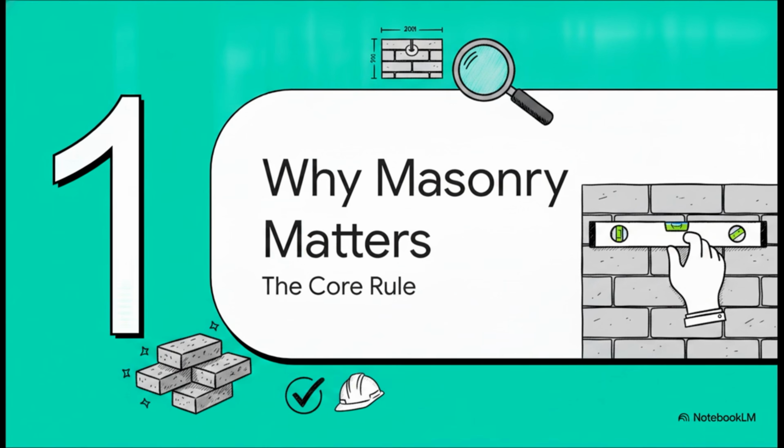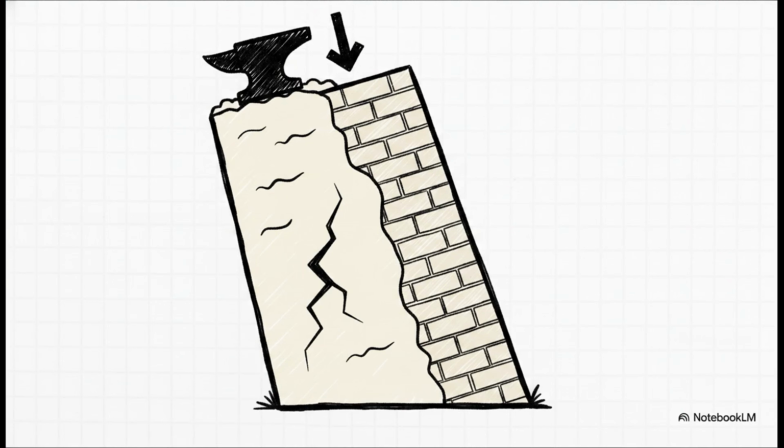Let's talk about why your rigorous QA/QC clearance here is simply non-negotiable. You've got to think about the cascading effect of poor masonry. Imagine a wall is built out of plumb. A mason might just try to compensate by slapping on extra plaster thickness on one side to make it look straight, right? But doing that drastically increases the dead load on the structure, and it needlessly bumps up your cement and sand consumption. Even worse, overly thick plaster is the primary culprit for shrinkage cracks and a wavy, totally unacceptable finish. Thorough checking up front saves you massive amounts of material and prevents highly expensive rework later.